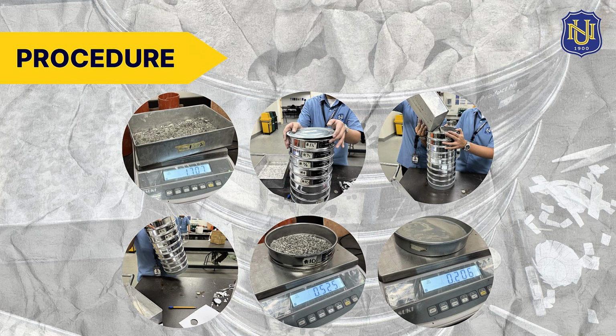Next, the sieves for fine aggregates are arranged according to their grading sizes. The sieve with the largest opening is placed at the top, while the smallest opening is placed at the bottom. The sand sample is then poured into the top sieve. Afterward, the sieve assembly is placed on the vibrating stand. The vibrating stand is operated for several minutes to allow the sand particles to pass through the sieves and separate according to size. After the vibration process is completed, the retained sand on each sieve is collected and weighed individually. These measurements represent the final weights of the graded sand particles.